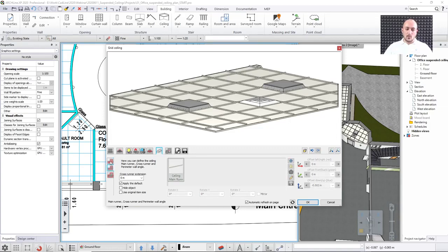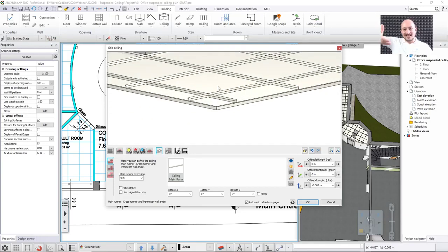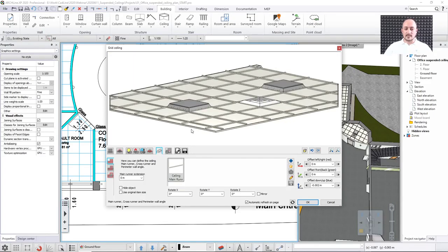As you can see, one is coming with a specific shift, so they are actually aligned properly to sit on top of each other if it is necessary. Okay, so this minus 0.02 elevates the grid to fit into this C shape, so it is resting on the top surface of this side item. Okay, so this is how detailed you can set this up, which is, I think, brilliant, and then you can fully customize it later on.